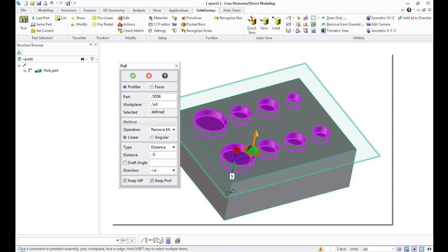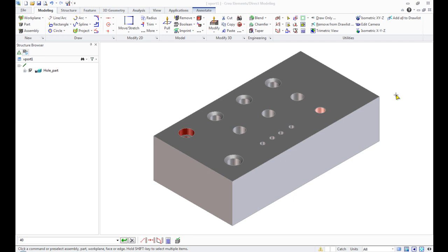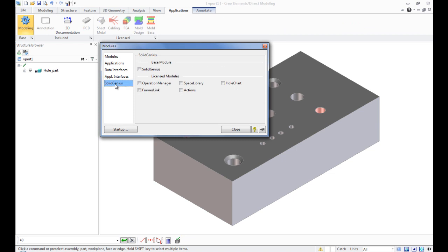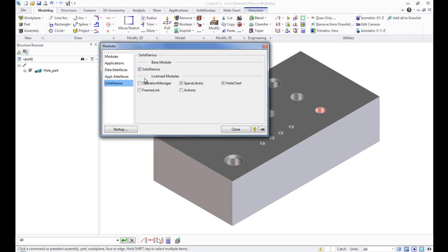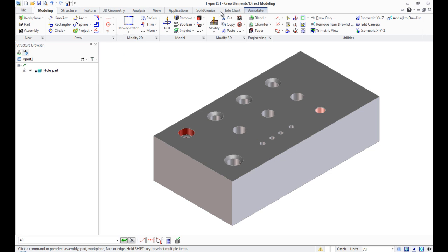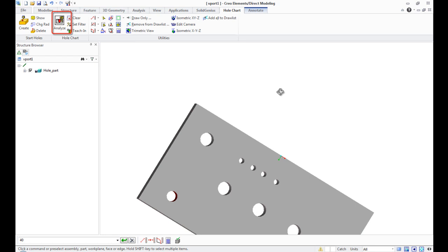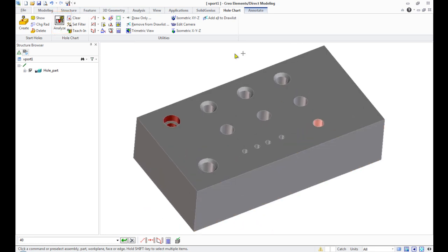The good advice is to produce your holes by using the machining model of Creo Elements Direct. When you use other methods, no hole info is contained as a 3D model, so the process becomes more difficult. In this case, the intelligent Analyze function of SolidGenius should be used before creating the hole chart. Analyze recognizes surfaces, intersections, and gives assumptions about the type of hole.